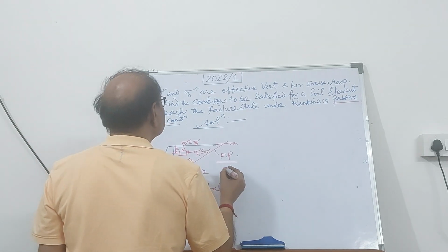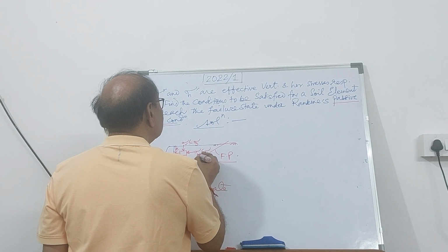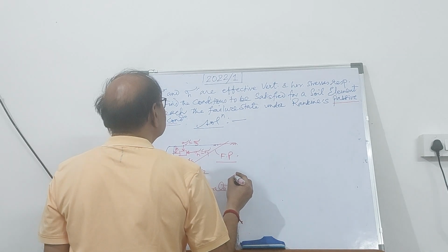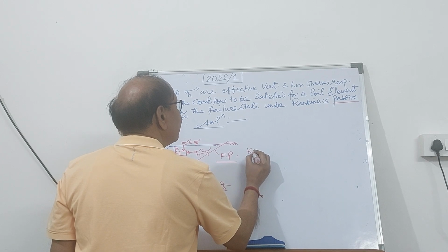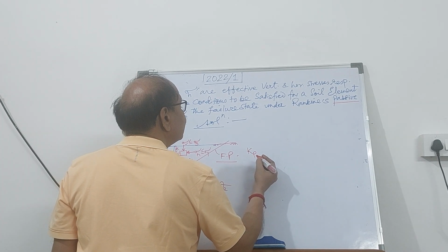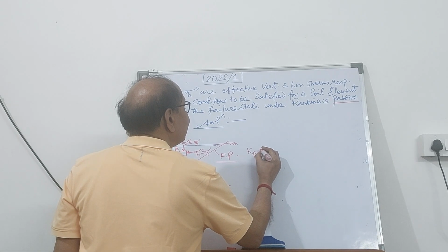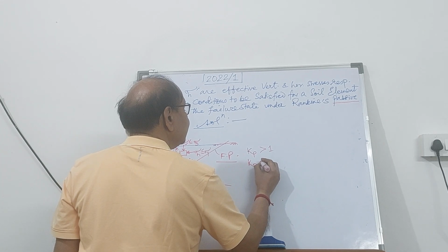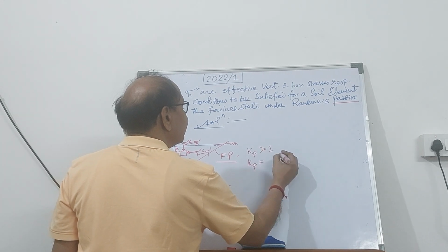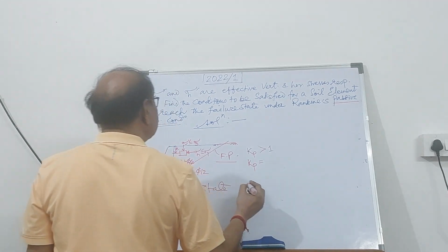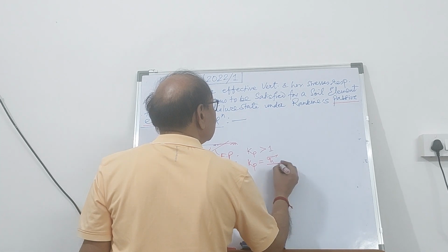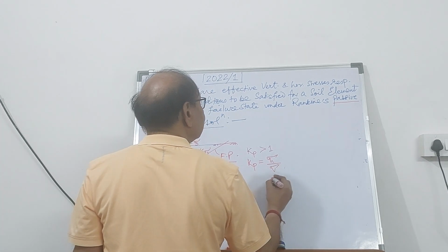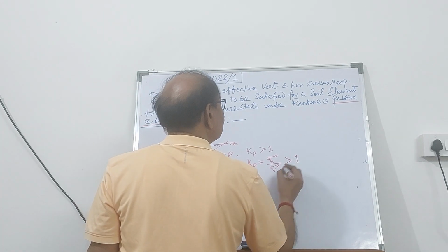In passive condition, the horizontal pressure is more than the vertical pressure. So you know, in passive, the coefficient of passive earth pressure, Kp, is always greater than 1. And what is Kp? It is the ratio of sigma H prime upon sigma V prime, which should be greater than 1.